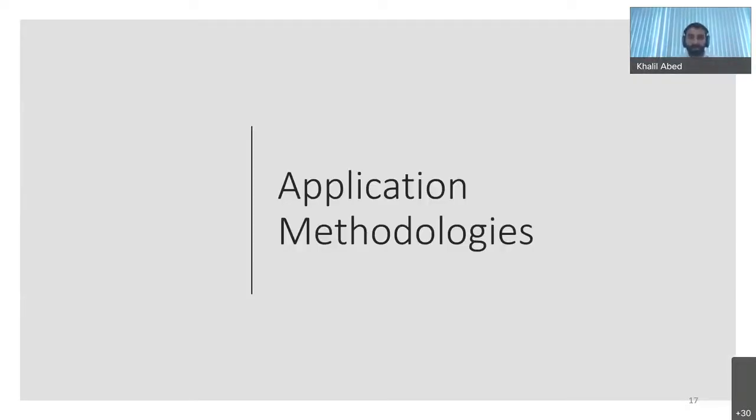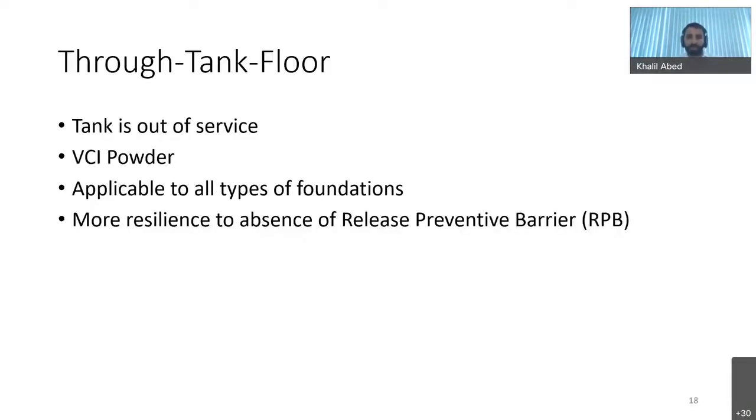Now we will be talking about application methodologies, the most common application methodologies for introducing vapor phase corrosion inhibitors under the tank. The first application methodology is through the tank floor. This application method is done when the tank, as it implies, is out of service for inspection, and it's applicable for all types of tank foundations.